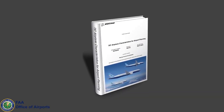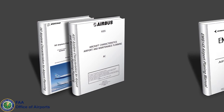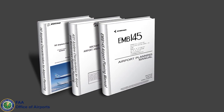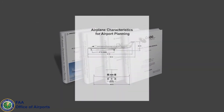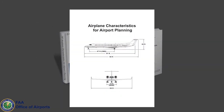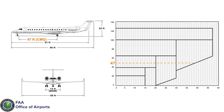A second method to determine an aircraft's TDG category is to use the aircraft's dimensions for CMG and MGW provided in the aircraft manufacturer's manuals. These manuals provide a wide range of each aircraft's dimensions, including CMG and MGW. In this example, plotting the dimensions for CMG and MGW from the manufacturer's manual on the TDG graph results in the TDG of Category 2B for this aircraft.